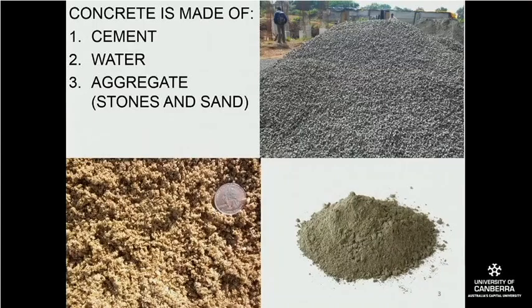So this is a very ancient way of making old-fashioned cement, which is to burn shells and then to mix it with sand and water to make a kind of weakish mortar, if you like, when compared to modern cements. However, this sand and lime method was used well into the early 20th century. So I think you could safely say it was used up until the 1930s.